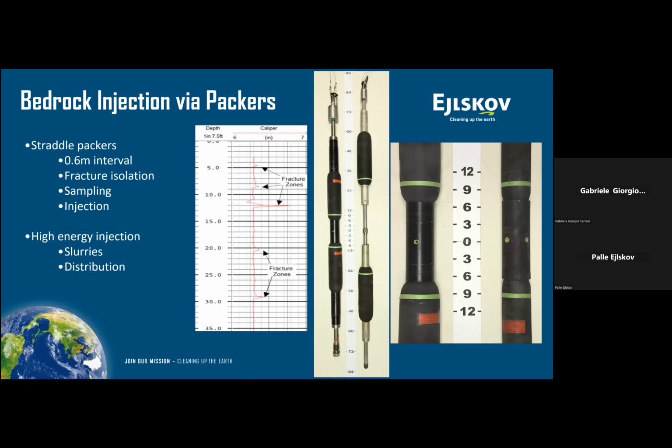When it comes to bedrock again, Mike, would you like to share a few words? Sure. I guess I should say we're doing more and more bedrock these days. I think a lot of the shallower overburden geologies have been remediated, and so here in the U.S. we're getting involved with more and more bedrock sites. Bedrock is obviously a different application technique. We can't use direct push. We're using straddle packers, and you'll see the picture in the middle on the left is of the custom packers that we had made for us, with about a 0.6 meter interval between the inflated packer glands that you see.